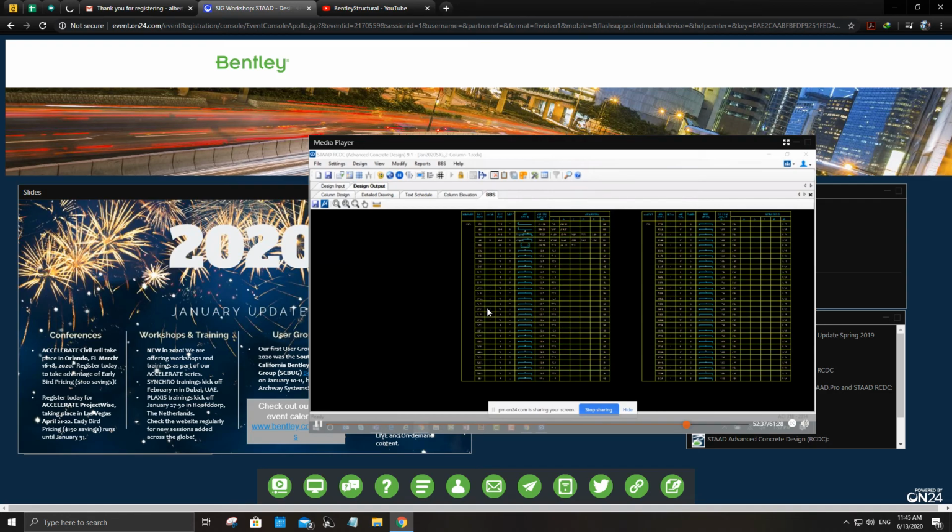Okay, someone asked, and this goes on to the parametric mesh, if the mesh density is different between two joined walls, will the software merge the common joints into the mesh for the two walls? And this would be along the height of the wall, I'm guessing. So if we take a look at a 90-degree intersection, would it automatically join the walls? If you do have a different mesh density, say my western wall, I did a 3-foot density, and my northern wall, I did a 2-foot density, it will not automatically match those up. It will match up the nodes that are there when it's created. It'll create the mesh when it's created.